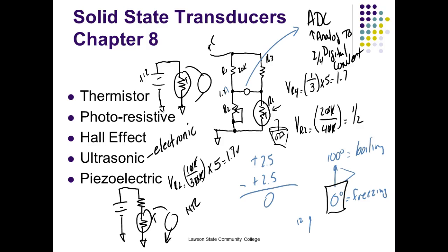So what do ultrasonic sensors do? They use sound to measure what they measure. They don't measure sound. Well, that's not true, they measure reflected sound. So what do they measure? These measure distance. That's their function in life. They send out a sound pulse and calculate the amount of time it takes to bounce back, which is proportional to distance.